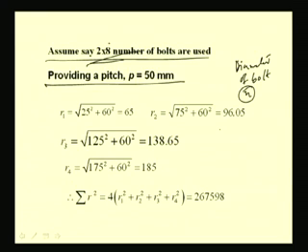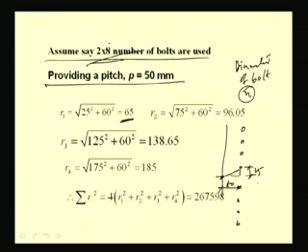That means we have 8 bolts. So, the CG will be here, and 8 bolts again will be here. So, R1, R2, R3, R4 can be found out. R1 will be what? This one is R1, that means this is 60 as we have assumed, and this will become 25. So, root over 25 square plus 60 square, which will become 65. So, R1 is becoming 65.